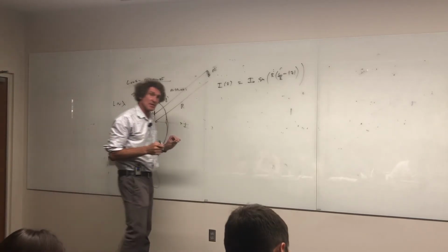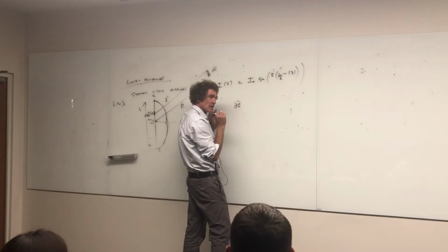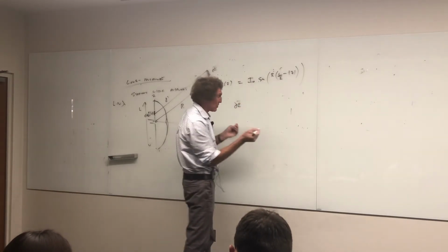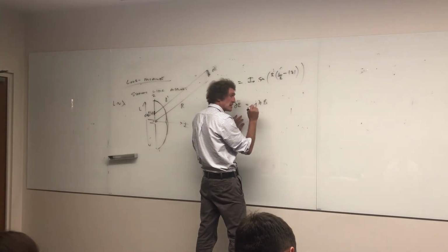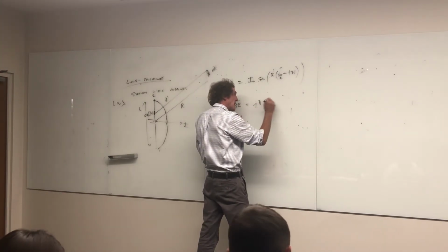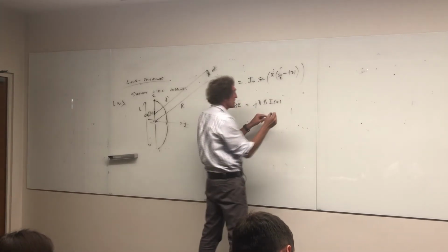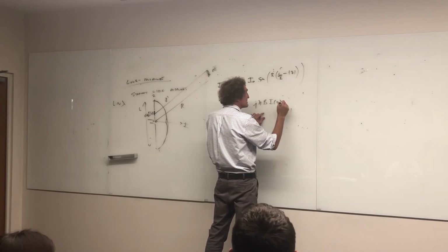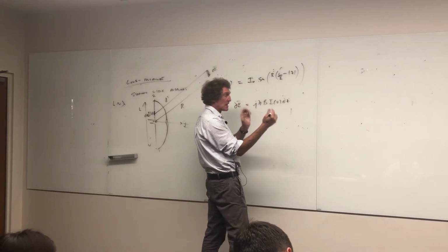So in the far field, what I can say is I have dE. Now, just hear me. I know for a short dipole, it would be equal to j eta beta, right? Then it would be my I of z here. That's the I value in the z. Then it's going to be I of z times dz, because it's got to have a thickness, or a length.